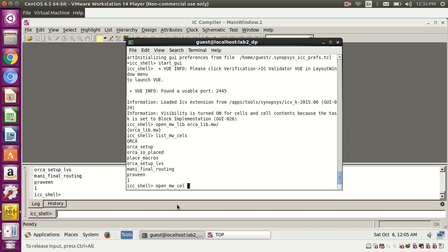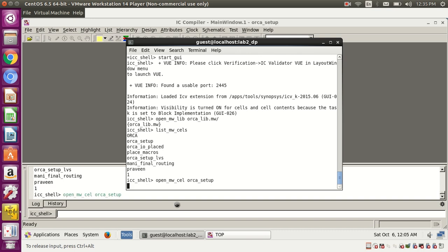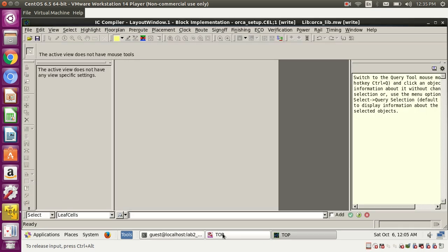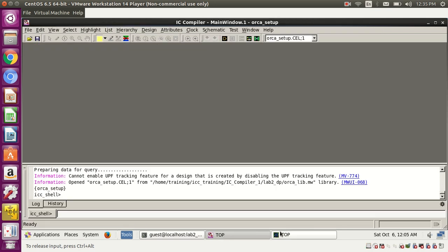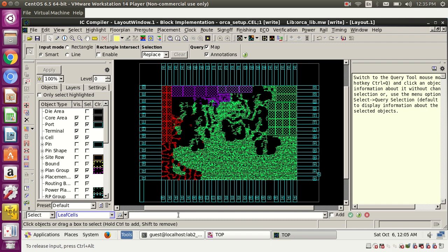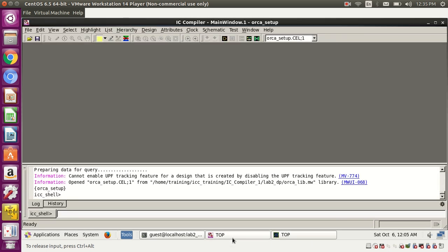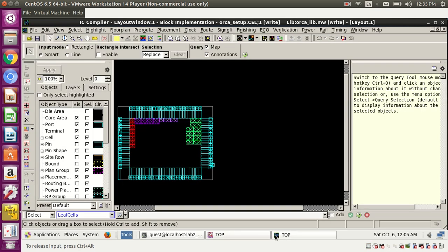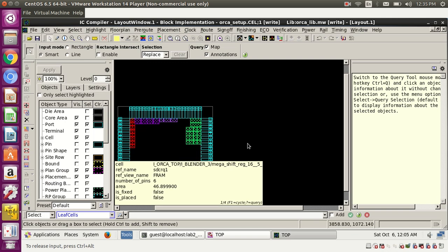So if this net has a driver here and a receiver there, normally before SI it has some 100 pF of load, picofarads of load. After calculating the SI, these two metal shapes are creating some 10 picofarads. So what the tool will do is for this shape add plus 10 and minus 10. It will calculate timing, adding and subtracting. For this it will add and subtract. If it is a data path, then it will do plus and minus.